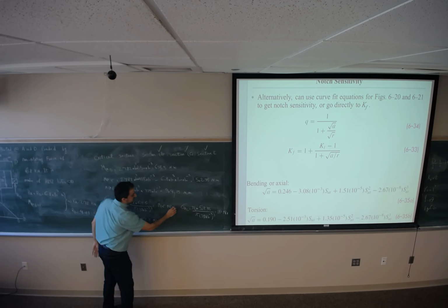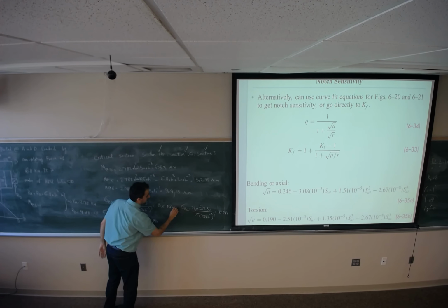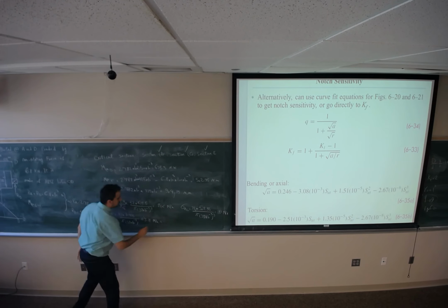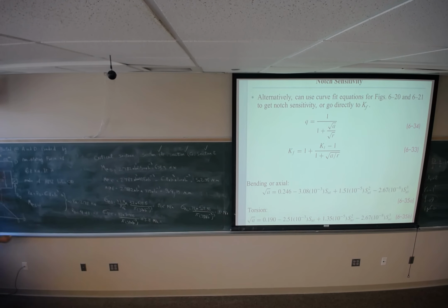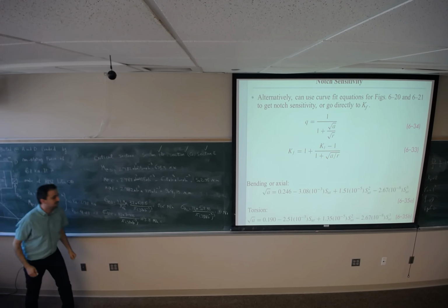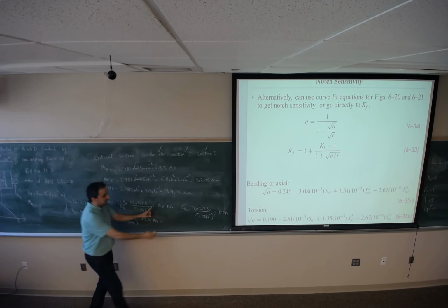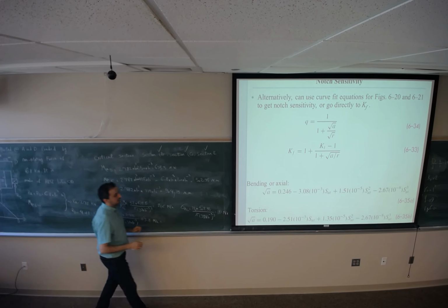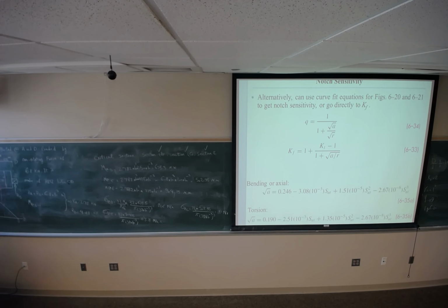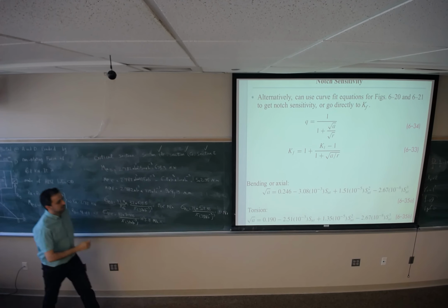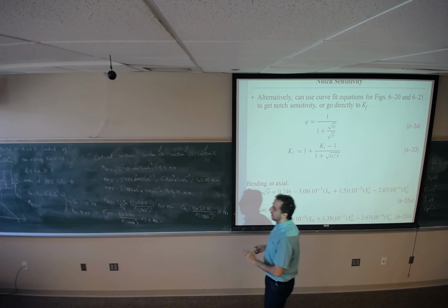The stress concentration factor doesn't have any effect on this one because we don't have any discontinuity here, so this value is going to be the same for the fatigue stress. But these two might change and they are going to increase. So either this section or this one would be the candidates for the critical section. We will answer this question shortly.